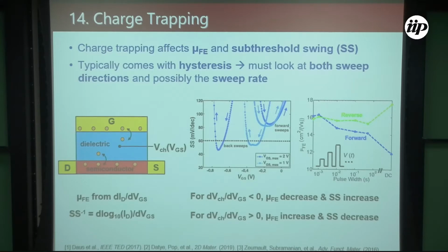So there are so many papers that we've read that have amazingly steep turn on, 70 millivolts per decade, in Nature, Science, right? And my postdoc says it's probably due to charge trapping in the dielectric. They probably didn't check their hysteresis. They probably just published the steeper looking curve, and he's very suspicious too. I'm telling you, my students are way tougher than I am.